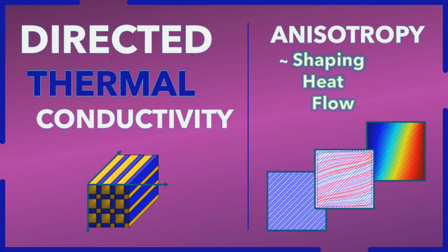You're catching on quickly. Now we need to bring another key player into the picture. Fourier's law. The laws of physics. I have a feeling things are about to get even more interesting. For sure. So Fourier's law is like the traffic cop directing heat flow, always pointing it from hotter areas to cooler ones in simple isotropic materials. It's pretty straightforward. A single thermal conductivity value tells us how efficiently that heat is moving. But we're not in simple material territory anymore, are we?